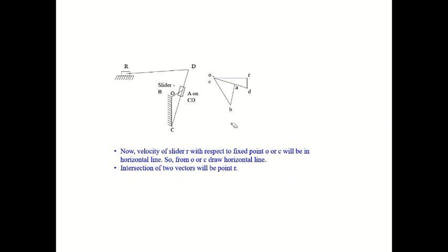That's all, we got all the points. Now what is the question? We should find the velocity of the piston. So measure the distance between O and R and multiply the value with the scale. I have used the scale as 0.5.